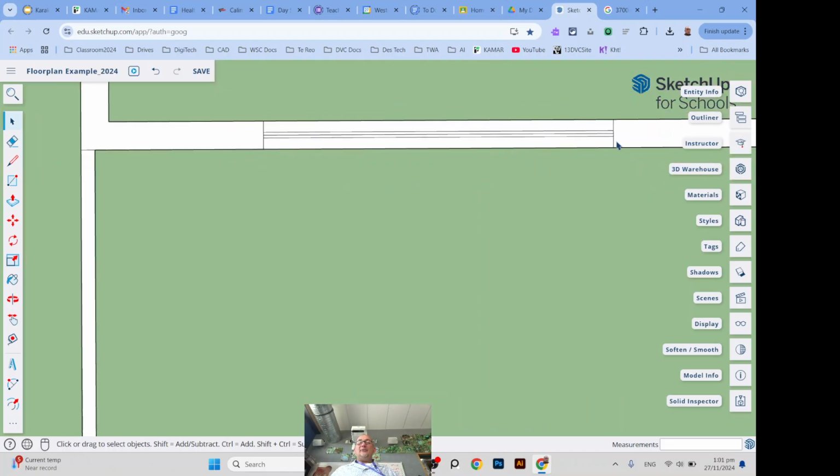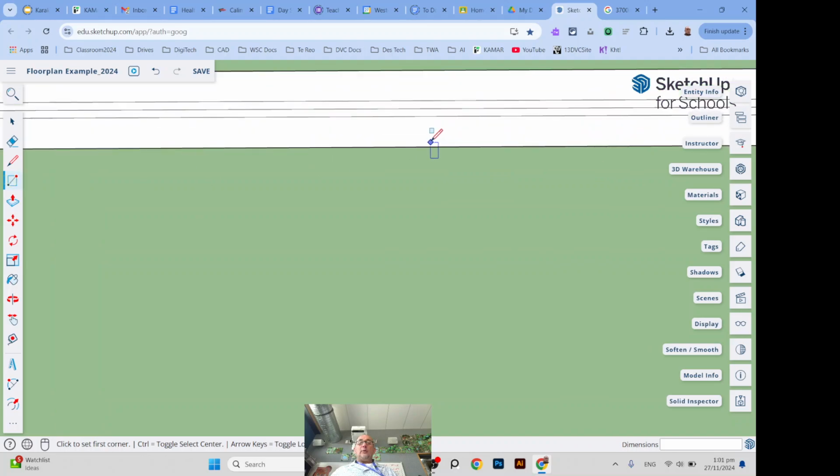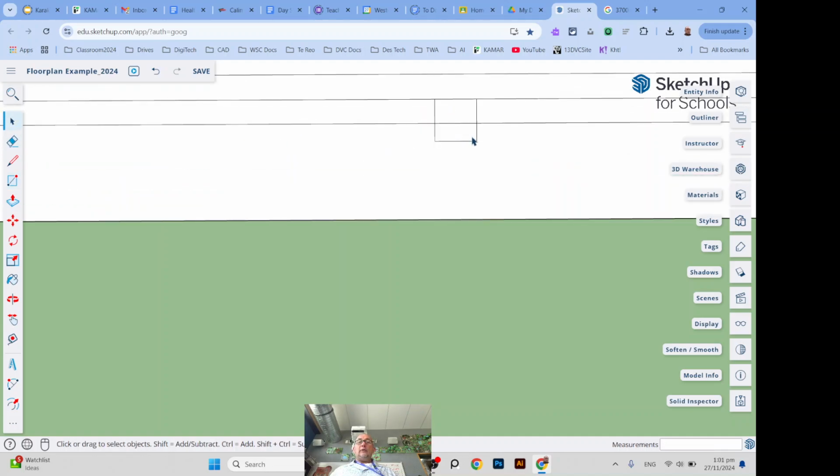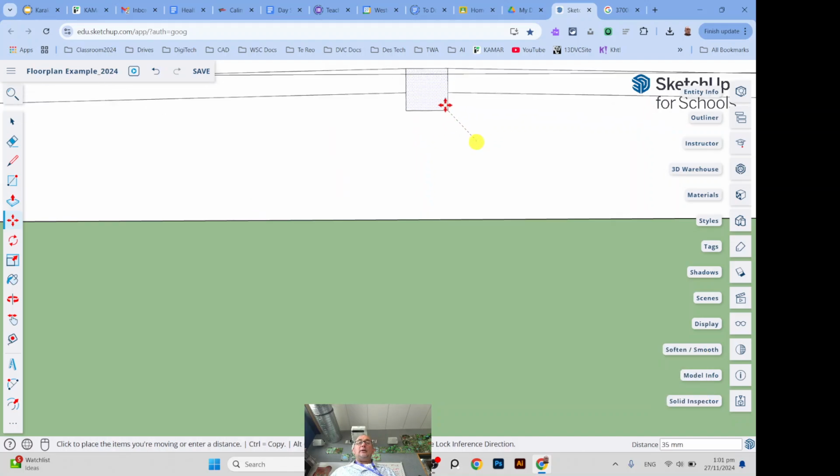Right, so again, this is a very simple window. Let's make it a little bit more sophisticated by adding some mullions. So for example, I could start by creating a rectangle starting from here, let's say that, right? Then I could take that rectangle, let's get rid of the interior part here. I could hit the M key, notice down here, the M key, to move it. And I could click here.